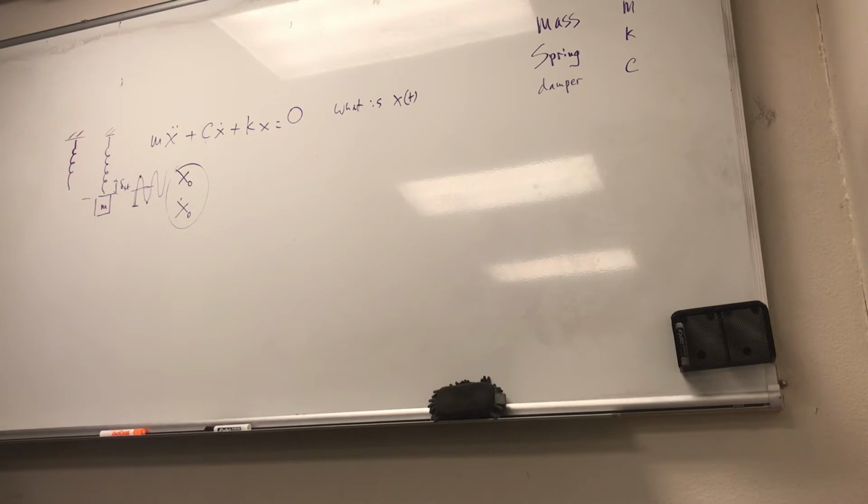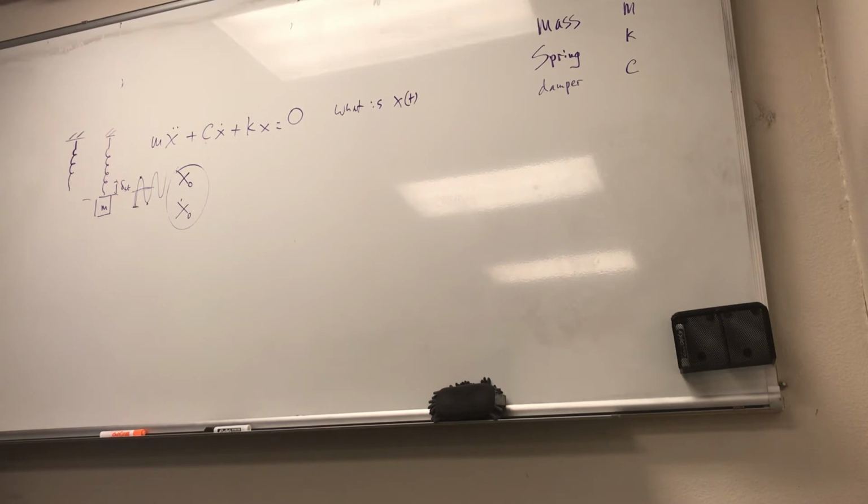So what are the elementary parts of a vibrating system? Obviously, it includes a means to store potential energy, a means to store kinetic energy, and a means by which energy gets lost. So you know which one is associated with which, right? The vibrating system involves the transfer of potential energy, usually in the spring, into kinetic energy, and then from kinetic back to potential energy, back and forth, okay? So we can visualize this very easily. If the system is damped, some energy is dissipated in each cycle and must be replaced by an external force if a state of vibration is to be maintained.